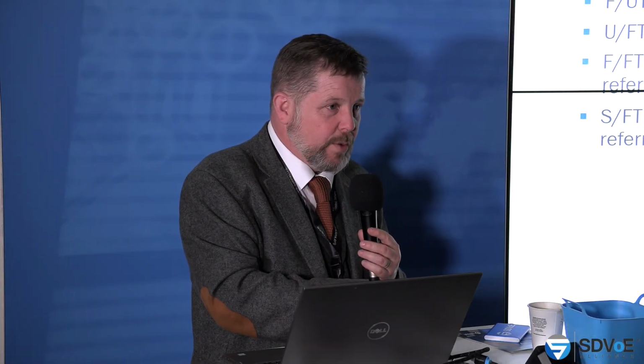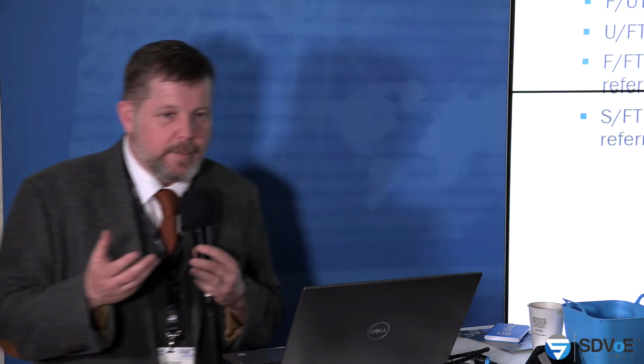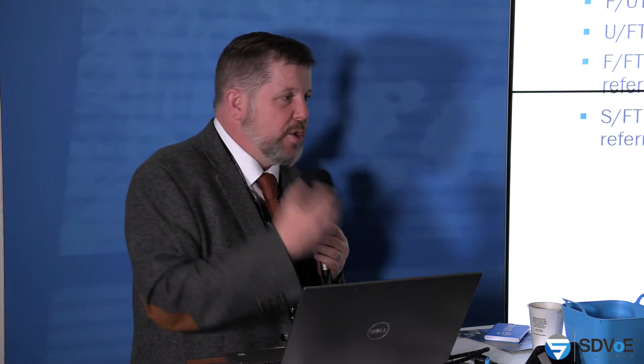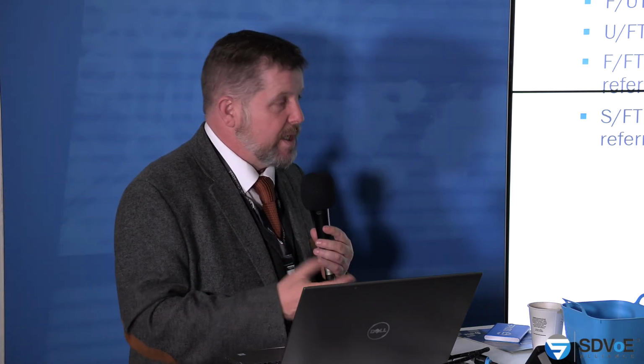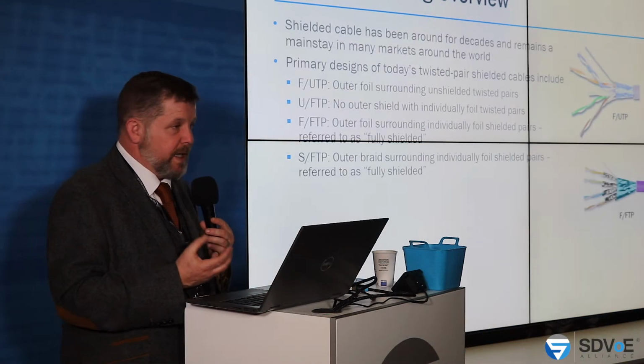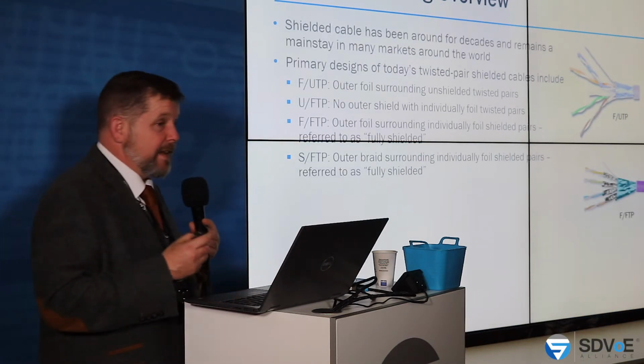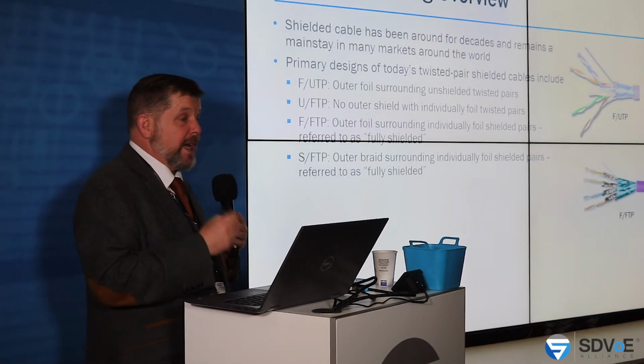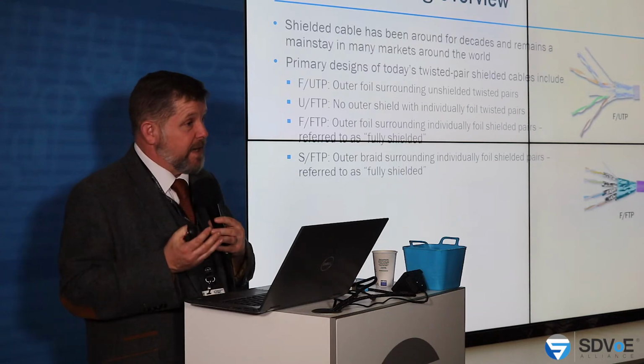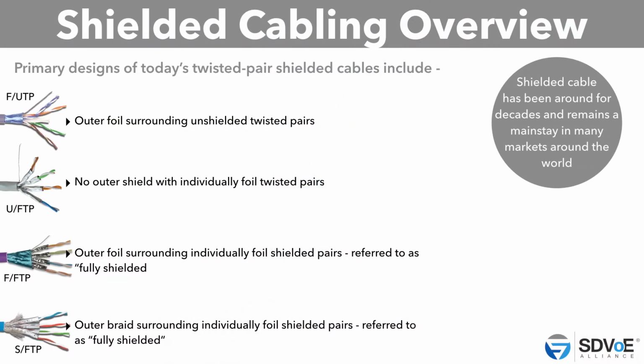affecting any other cable. So when we start talking about 10 gigabit, we are talking about a huge amount of transmission signal, high amounts of transmission frequency that we cannot afford to let be corrupted, and we cannot let that cable affect anything else in its environment. So most customers are now literally moving towards shielded cables because these offer the best protection in terms of immunity.